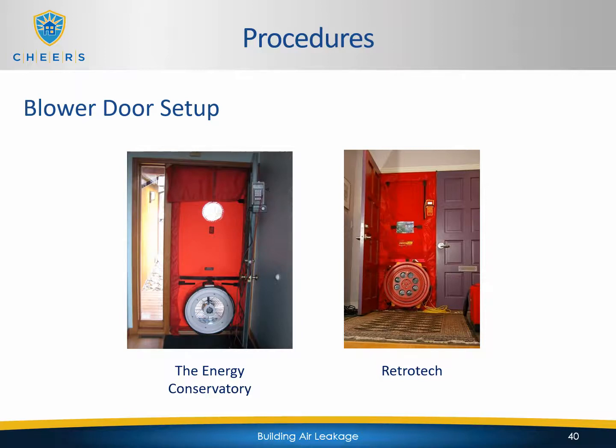You might get in a situation where the blower door is not big enough for the opening. You might have an 8-foot door, and maybe the blower door doesn't quite reach all the way up for whatever reason. You can tape the excess shut as long as it's completely sealed from the outside. So as long as you tape it up and there are no infiltration points within your taping and sealing, you're fine as well.